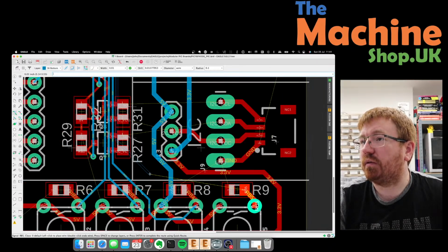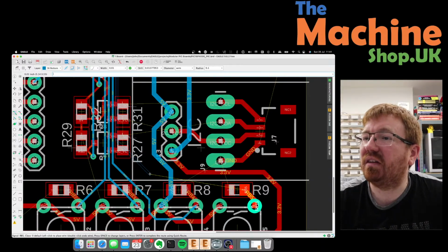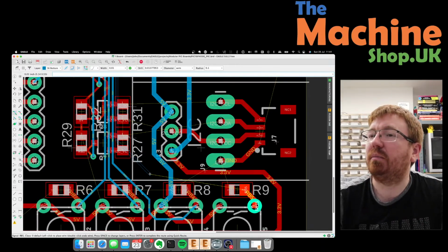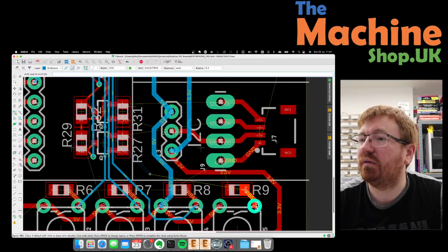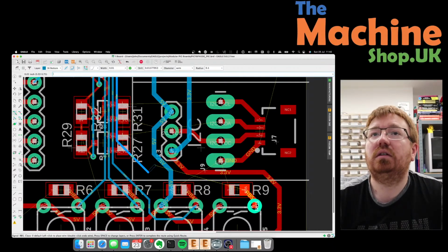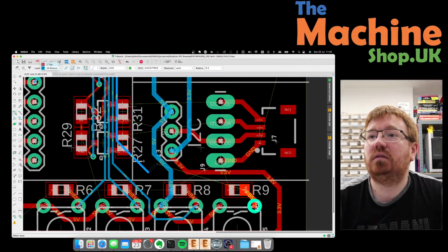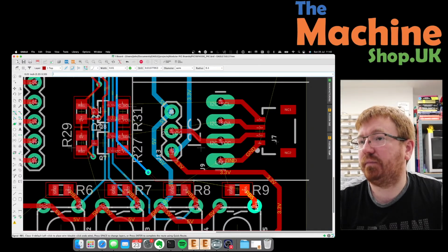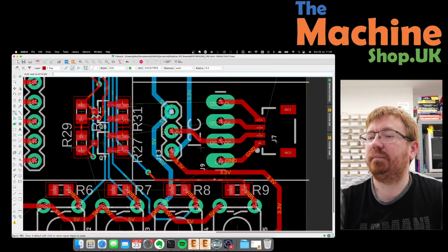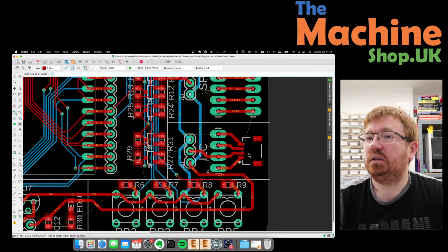Does that 3.3 volt need to be? Yeah, it does need to be fairly thick because of the amount of current it's going to be carrying for the 3.3 volt. Let's see if it fits. Let's chuck that. Let's not get it near the silk screen. Fire. Let's see. Yeah. All right. That'll do. There we go. Cool. So that's 5-volt and 5-volt. That's fine. I could connect that through there.